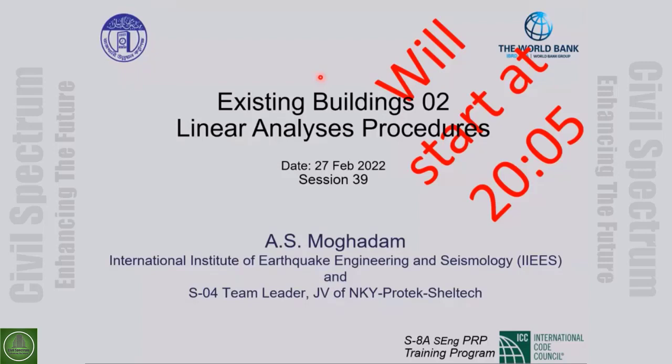So it is possible to reduce all the forces expected to be applied by an earthquake to the building for a specific level by an R factor, because by ensuring the implementation of those detailing, we can be sure that the ductility provided in the building is more than the damage that is expected.